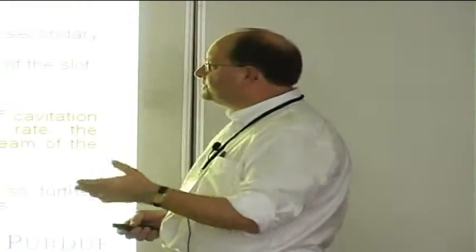I keep talking about cavitation. That's the most visible thing. It's easiest to point your finger at it and say it's long, it's short, it's unsteady. But really, there's a lot going on here. And this is creating the flow that feeds wave growth and primary atomization outside the nozzle. So what's going on inside seems to be affecting what's going on outside.